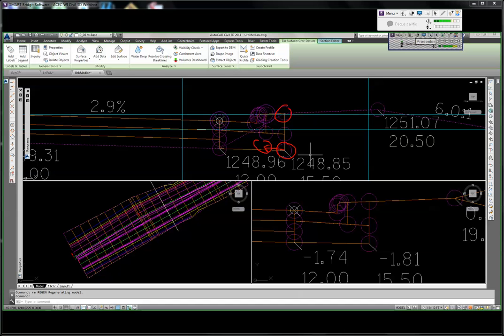The reason why I like to do it at the bottom here is I simply take the name of this code here and put it into this point here. What that means is the corridor already is looking for this point. It already knows it exists, and it's already using it, probably, if you're at this phase of your design. By using that point code over, it says, well, I see two of the same code, but I'm getting to this one first, and now I can get up to the top portion of this without an issue. So that's the way that I like to handle this myself.